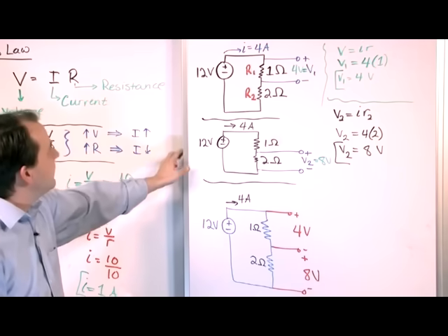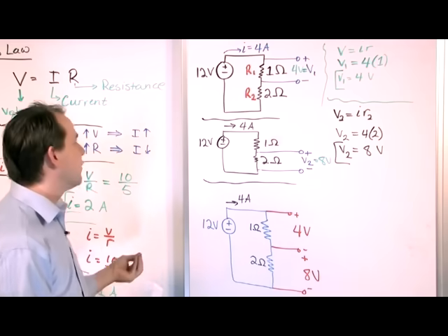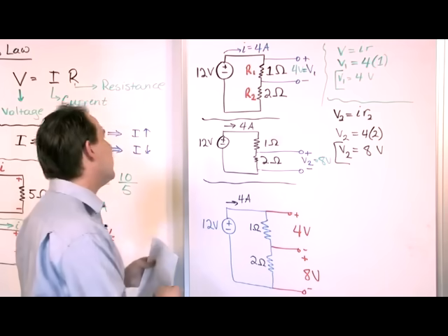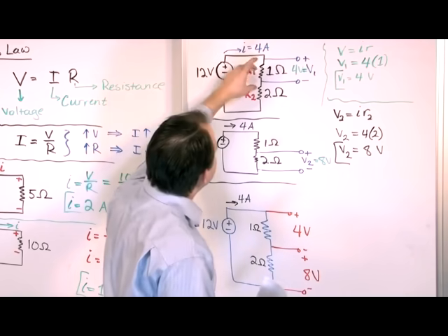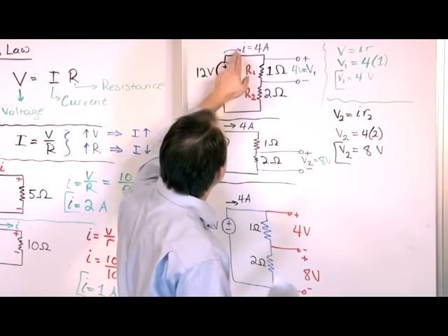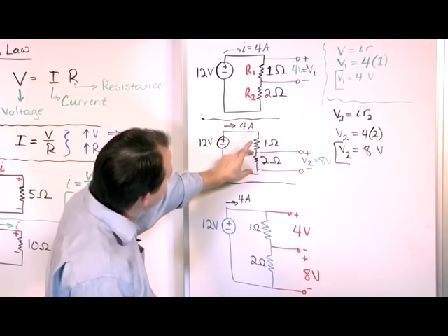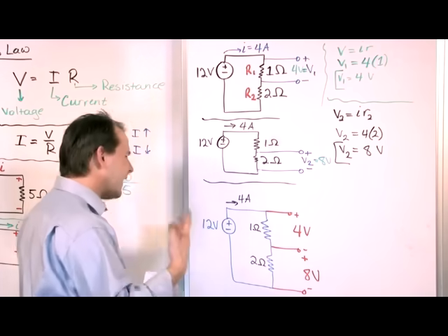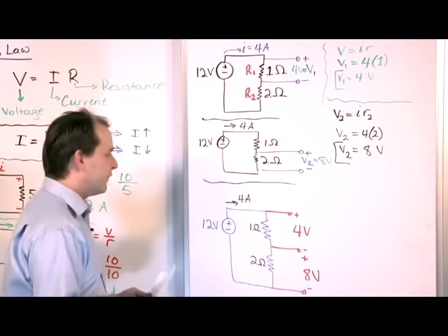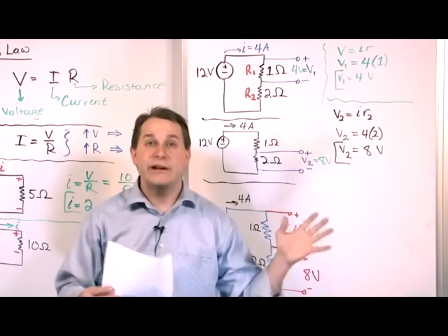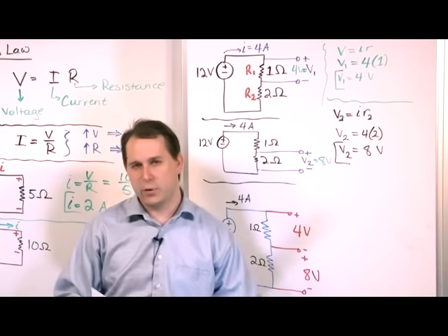And then finally, we did this problem, which is very telling and very helpful for you later on, because what it's basically trying to show you is that these circuits don't have to be quite so simple. If you just know the resistance and the current going through something, you can calculate the voltage across an element. You can calculate the voltage across another element. And very important, you can add these 2 voltages up, and that's always going to equal the source voltage. There are a lot of things in here that I could talk a lot more about, but in truth, we're going to get to all of them in even more detail as we go through the next few sections.